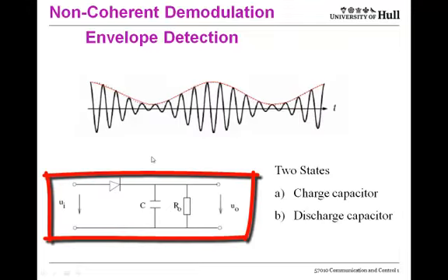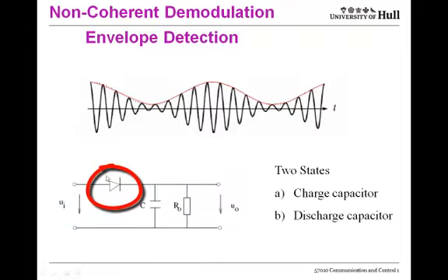So here we have a circuit that attempts to achieve that. It has a non-linear element, as it needs to move between different frequencies. This is called an envelope detector. It has an input UI, which will be the modulated signal, and an output UO, which approximates this red line of joining the peaks of our signal. In the next slide we see how this system works.